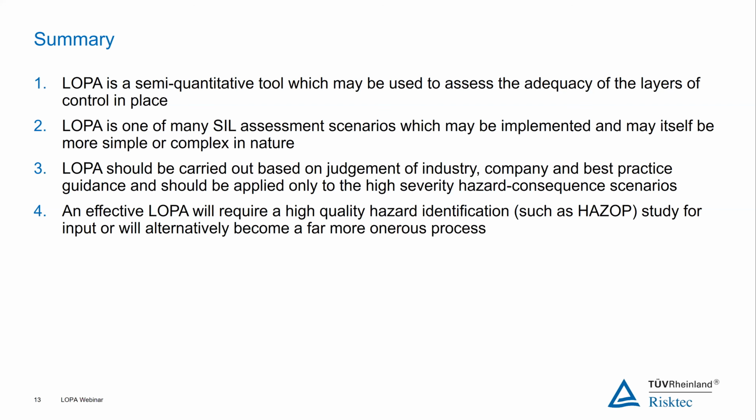And finally, an effective LOPA will require an effective and a high quality hazard identification study as an input, such as a HAZOP. Otherwise, LOPA will become far more onerous and may even become impossible depending on the quality of that input that you have in place.